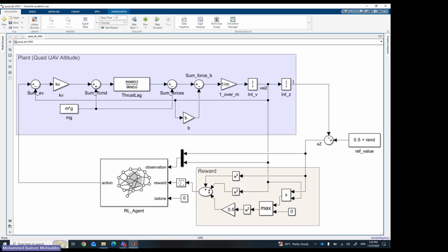When you run something in Simulink, that might not directly show in MATLAB, but for ease of access, you use a To Workspace block. Then you send whatever signals you want to the MATLAB workspace. Once you have it there, you can simply use a plot function and plot the graph. From that graph, there are tools within the plot function that you can use to select the peak value, the lowest value, the steady state value. From that, you will get the performance characteristics or performance metrics. Clear?